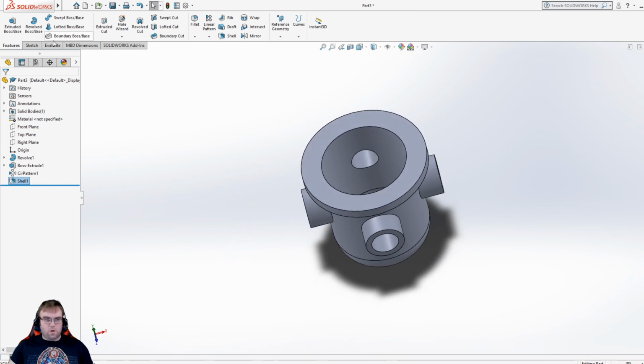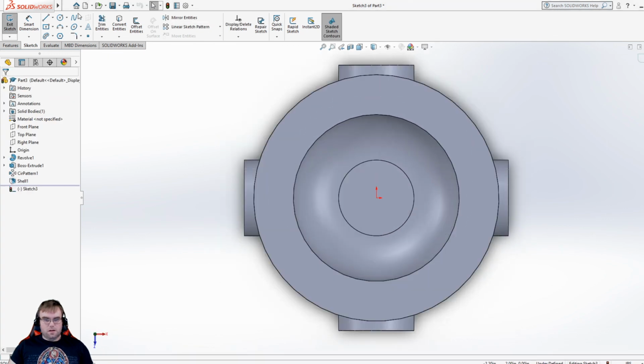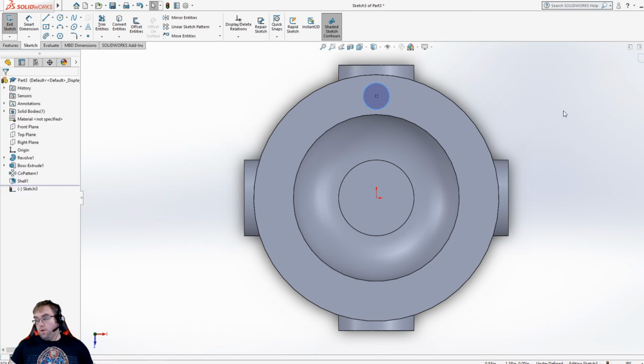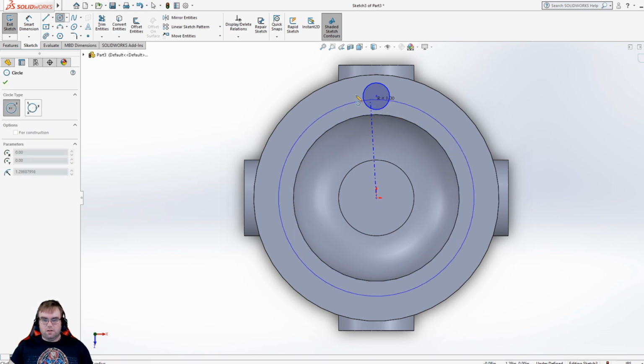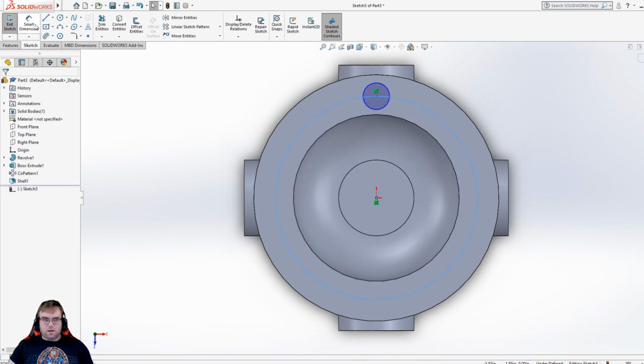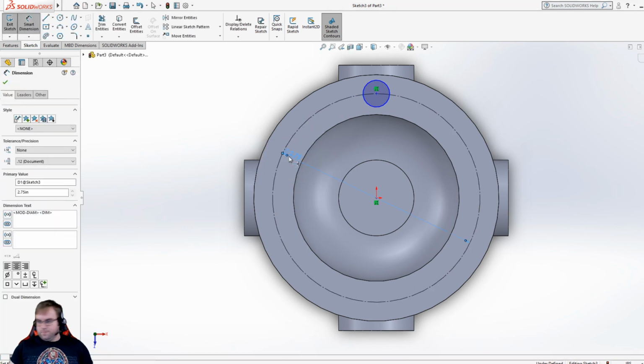So now I'm going to put the holes in on top. So do a sketch there. I'm going to put 8 circles. Well, I'm going to put 1 circle, then I'll pattern the feature. And it's calling out a common bolt diameter of 2.75, so I'm just going to put in a reference circle. Draw it out like this for construction, and I'll dimension it to be 2.75. And those bolt holes are 0.25.